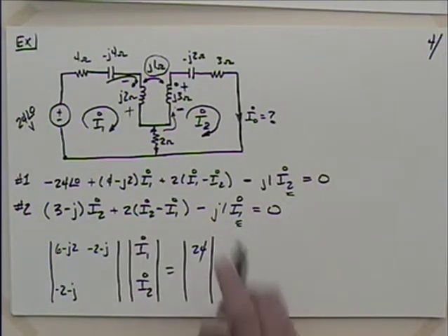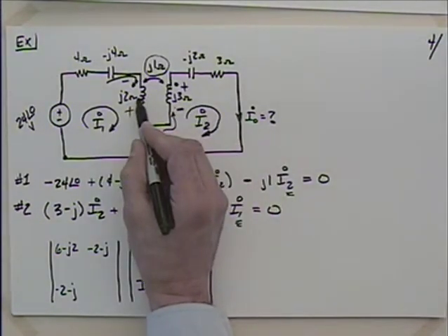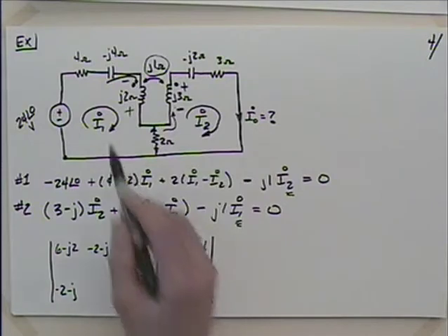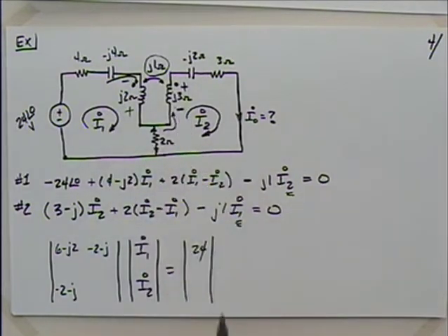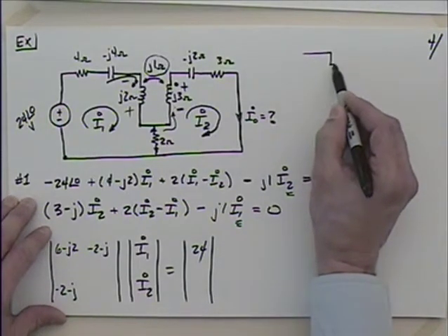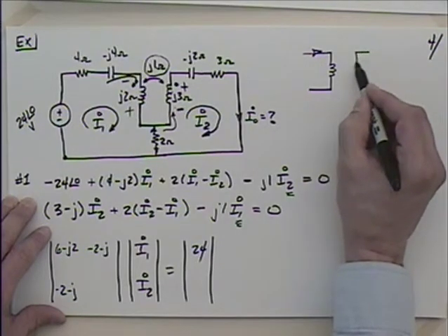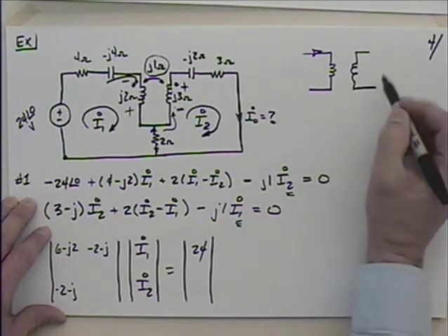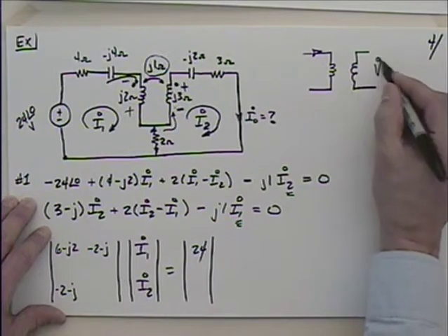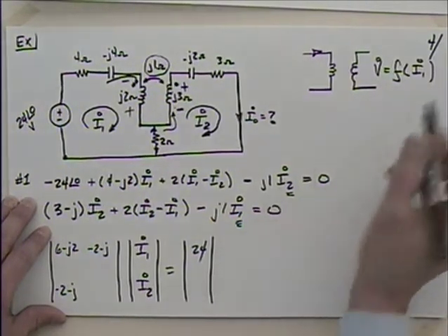Yeah, it's because this current here, I2, is inducing a voltage over here. And conversely, this current I1 is inducing a voltage over here. So that's what I said when we first started studying transformers. Everyone is pretty comfortable with taking this transformer and having this current, I1, induce a voltage over here, so have this voltage here as some function of I1.